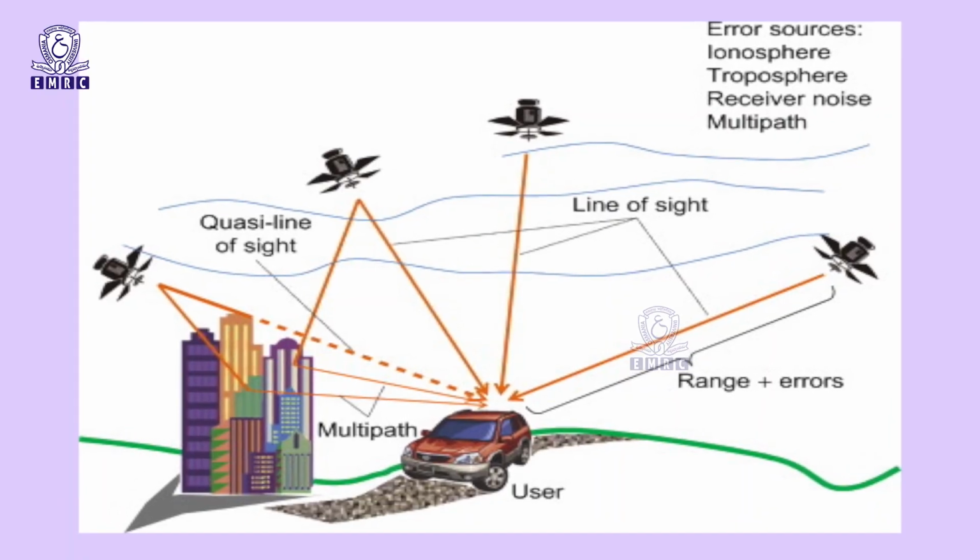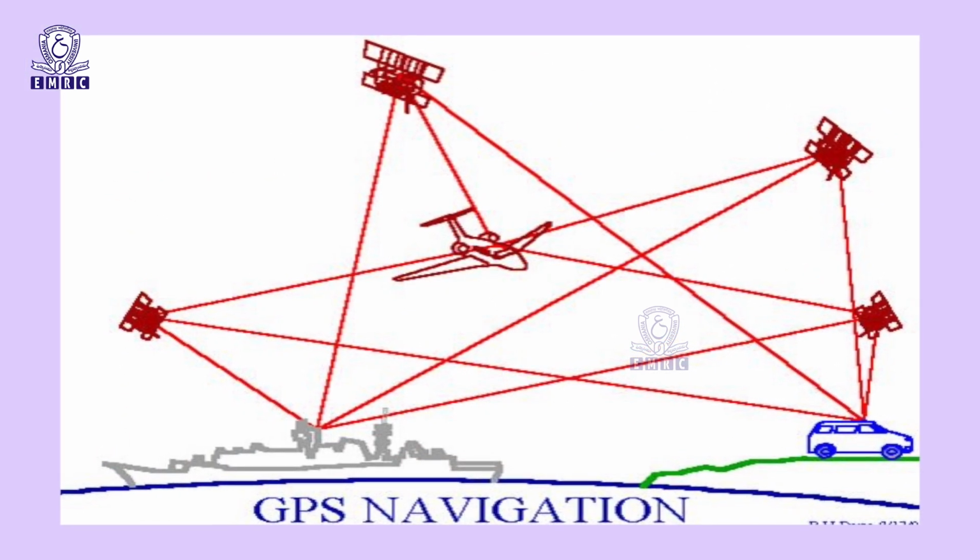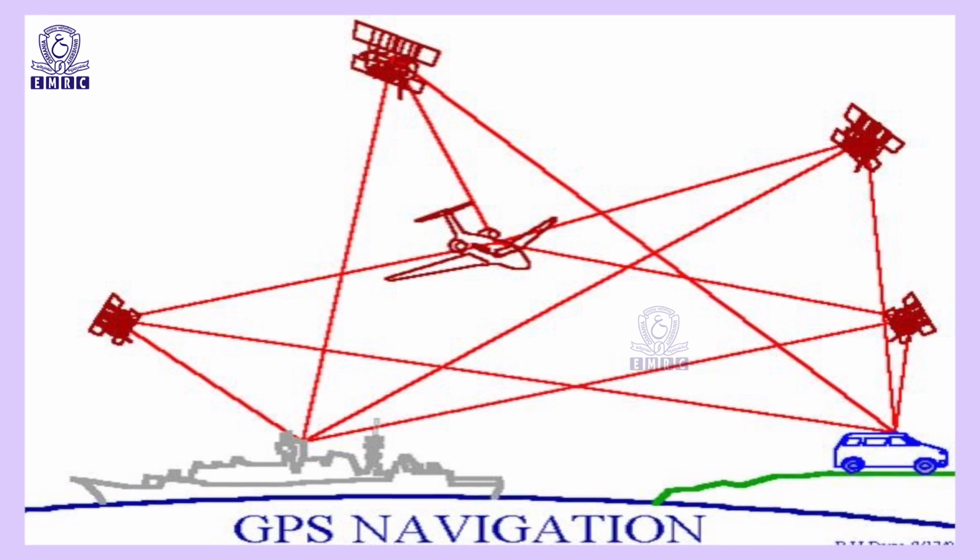The master station collects the data about the satellites of this system continuously from the other tracking stations. The master control segment processes the tracking data for computation of satellite ephemerides, or coordinates, and satellite clock parameters. The master control station uploads ephemeris and clock data to the satellite vehicles. The satellite vehicles then send a subset of the orbital ephemeris data to GPS receivers over radio signals.